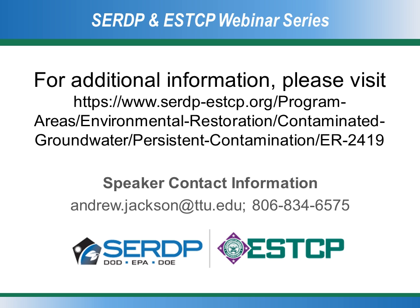Thank you. For the concentration decay of the velocity tracer, is the rate measured in real time or after the removal of the probe? After removal of the probe. So the probe is removed, and from each one of those velocity cells, the water is removed, and the bromide concentration is determined by ion chromatography.